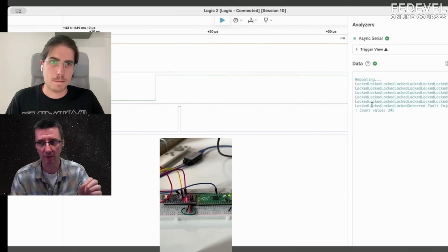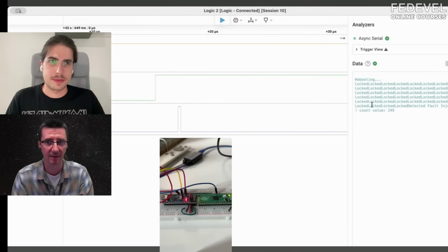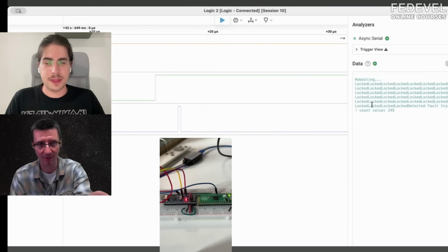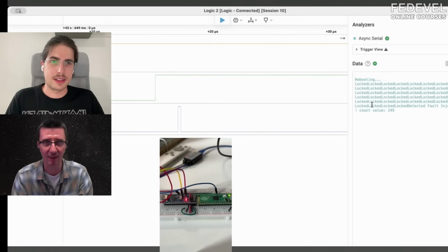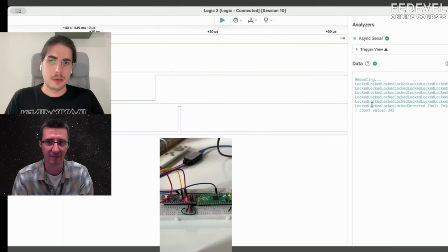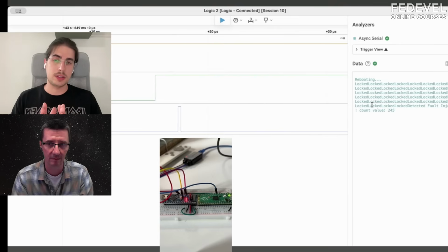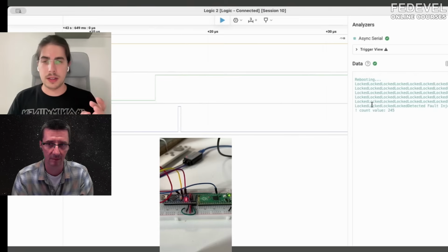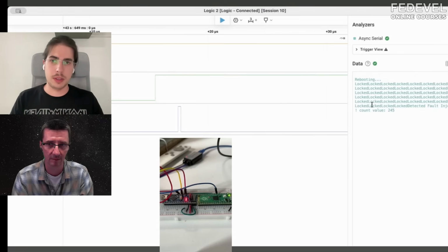Because right now you don't exactly know which instruction you skipped. Basically you know based on the output from the serial console, but you can't really control which one you are going to hit. Yeah. We could write the firmware in different ways to know. For instance, we could use multiple registers and try to only fault a certain one, all instructions that affect a certain register and not other instructions that affect other registers. In that case, we can fine tune the timing even more.